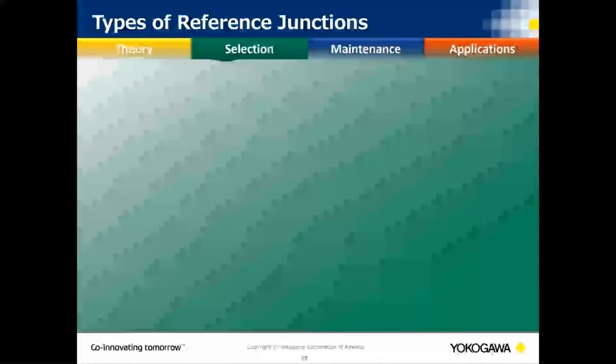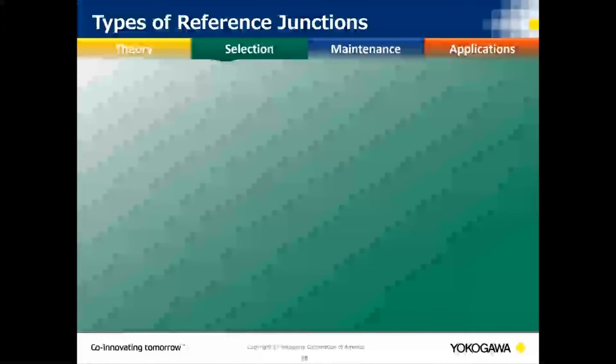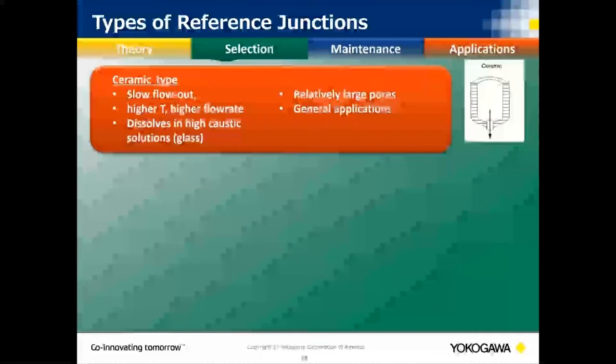is traditionally the same pH reference that you have. So if you have a pH electrode and an ORP electrode in the same line, even though you have two different measurements, you're going to have the same problems. So we need to make sure we have the right junction, the right reference fill solution, and proper cleaning. Remember, we talked about this briefly with the pH.